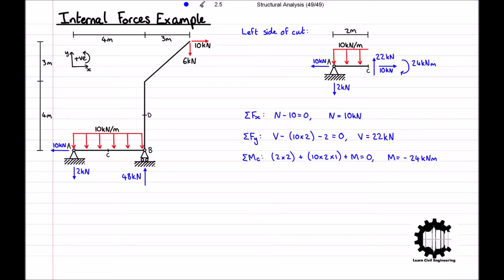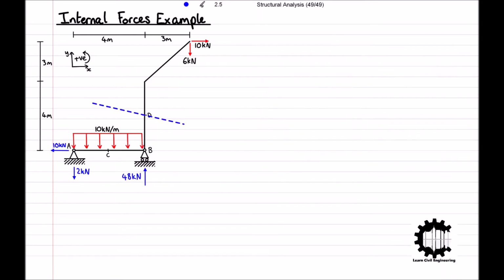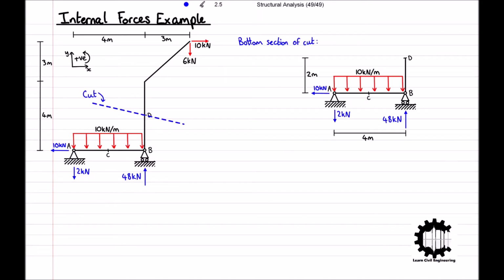Welcome back if you did attempt to calculate the internal forces at point D. For this, we will cut the bent bar at point D and consider only the bottom section like so. Again, we must annotate the unknown internal forces at point D, and referencing back to our positive force diagram for a vertical bar, the corresponding positive internal forces look like this.